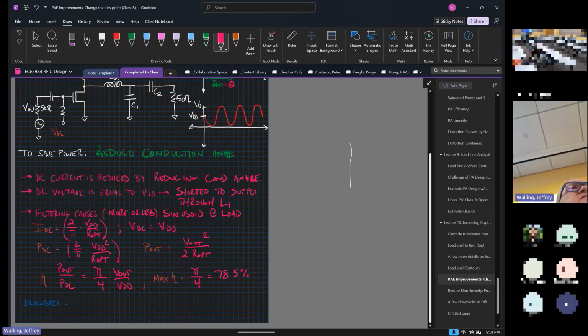And of course, that happens in our RF amplifiers as well, but this is still considered to be a linear power amplifier because as I increase the input power, the output power will increase linearly proportional to that input. There might be some distortion in the waveform that will be transferred to harmonics. So the waveform itself might be distorted. I might be transferring power to frequencies that I don't want them at, but more or less as I increase the power, it's going to increase the output power linearly by the same proportion. That's why they call this a linear power amplifier.